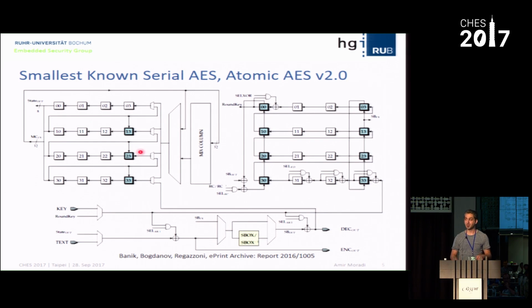The gray ones are the scan flip-flops, meaning you have here 8-bit multiplied by 3, I mean 3 times 8-bit scan flip-flops. And here for the key scheduling you also have 8 times 8-bit scan flip-flops, and then everything here is shifted to the left, from right to left, to the state. The key scheduling actually does the same, but for doing particular parts of the key schedule, it also has to shift in vertical direction. For that reason, they need to employ the scan flip-flops.